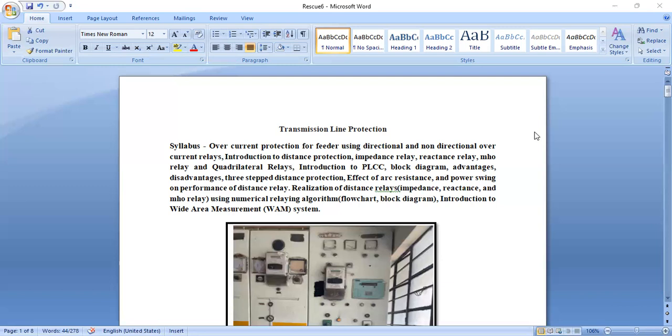Similarly, overload, earth fault, through fault, then large internal faults. Large internal faults, that means phase to phase fault, phase to ground fault, and below oil level fault. Then the high fault in the tap changer. Which type of protection is employed for these abnormalities of the transformer we have already done. Basically, differential protection we can use for the transformer and alternator also.